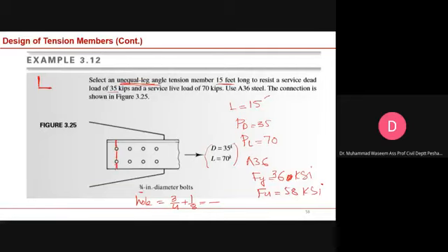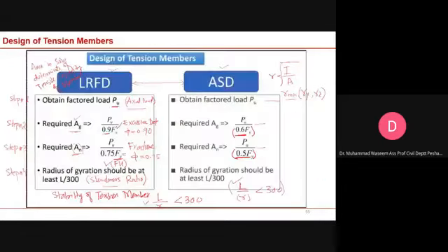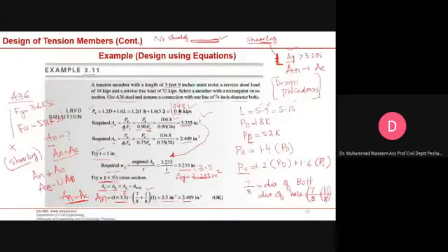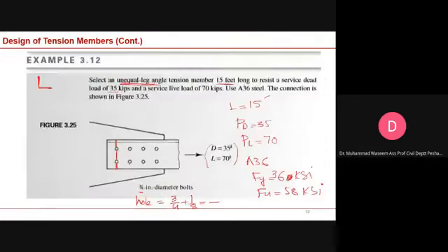Okay, in the last example we had, let me check, where is that problem? It says there is a line of bolts. Okay, so that's why we subtracted just 1 hole area. Okay, now in this example we are going to subtract the 2 holes area from the gross area.